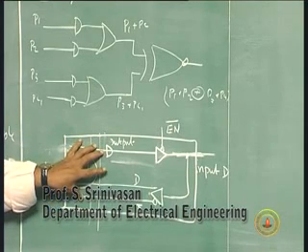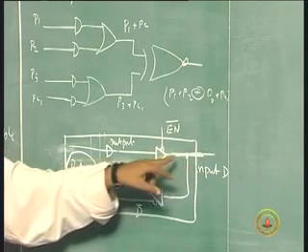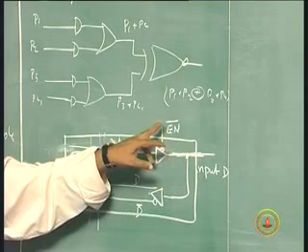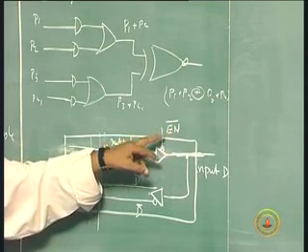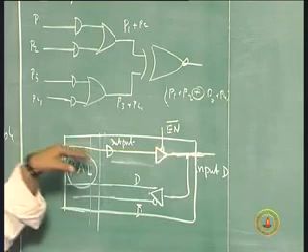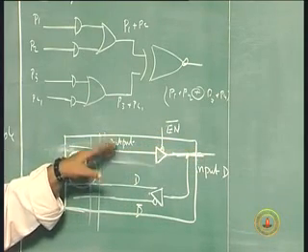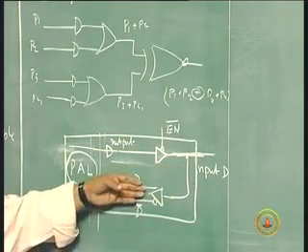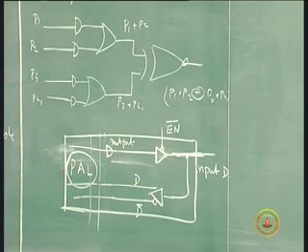What we had originally, normally I would have had this output available to you. Now I am putting this extra logic here, which can keep it as an output if you want by making En equal to 0. If you don't want this to be an output, I make En 1 and this is disconnected. Actually this AND gate is not available as output. This OR gate, or whatever, this is an OR function, it's not available. So I take this and use it as an input with this one complement and all that, and then it will be also used in my synthesis. This is my programmable I/O.